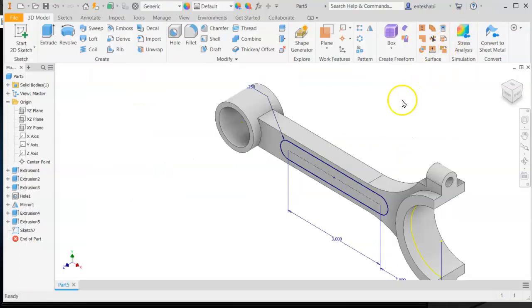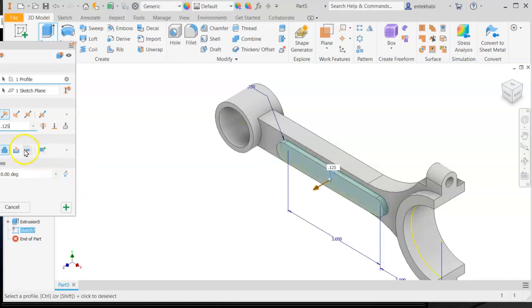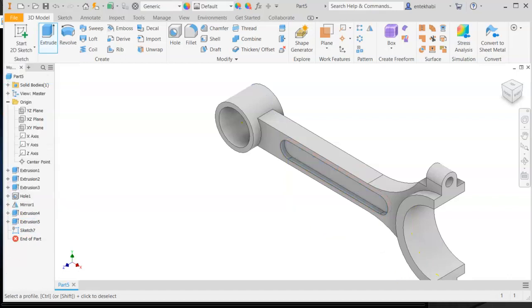Let's continue on this extrude. We're going to extrude, use, this time we have to define exactly 0.125 depth and change the directions to go opposite direction and cut. Make sure you select it. All right, so you can repeat this step on the other end by rotating to the other end, or use the mirror tool. That's the more convenient to do. Take advantage of this mirror tool.